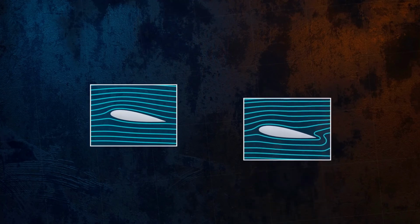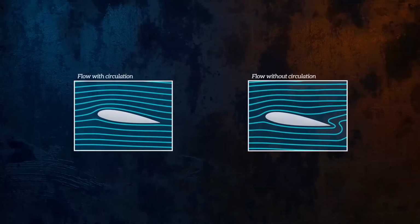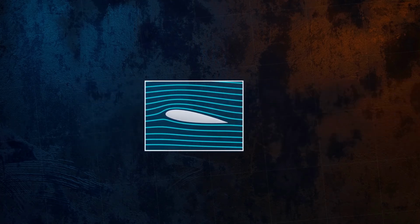Without circulation, the flow around the airfoil would look like this. This is clearly non-physical, since the fluid cannot turn such a sharp corner at the trailing edge, and so the airfoil must be generating some circulation.